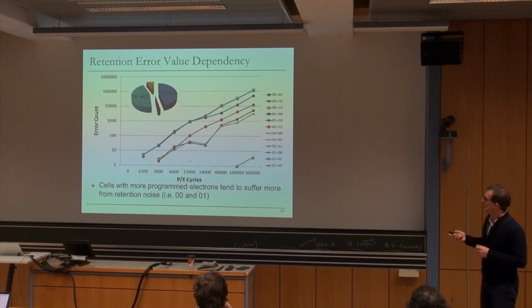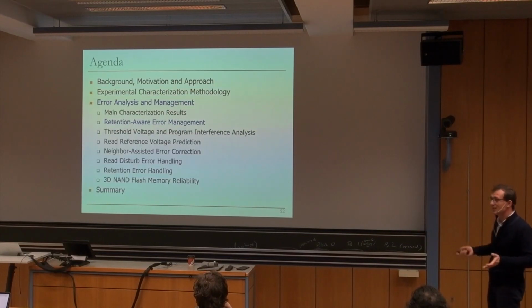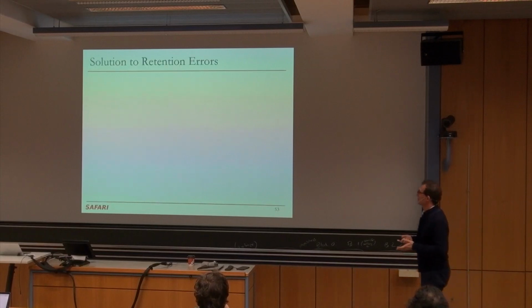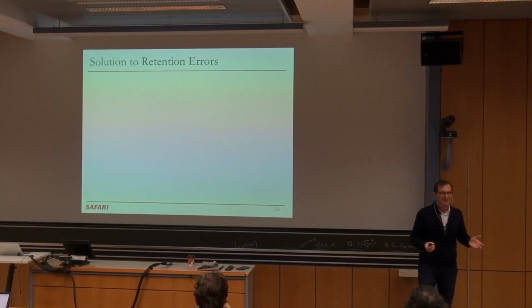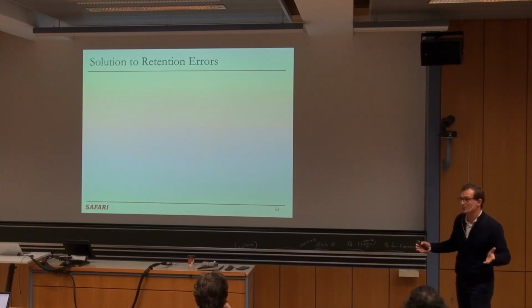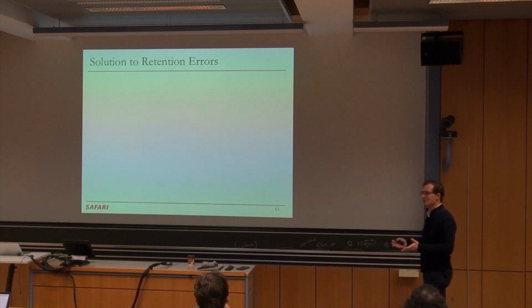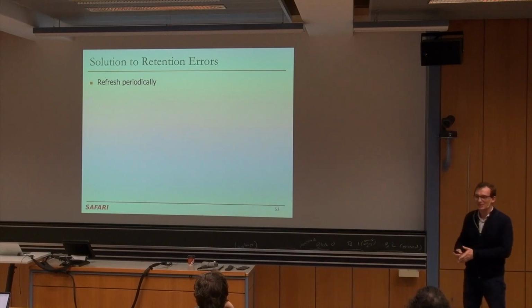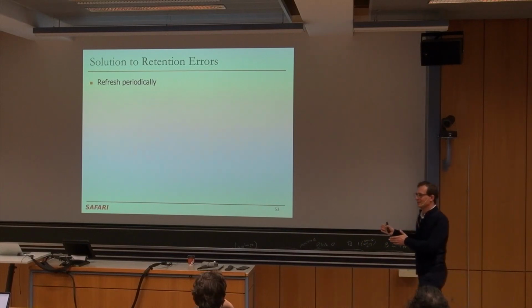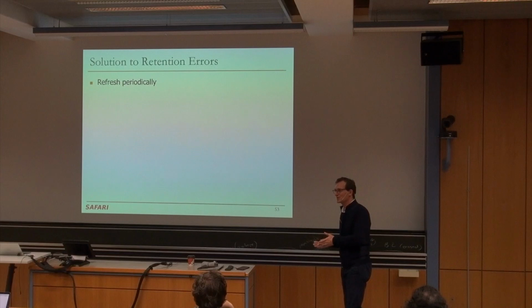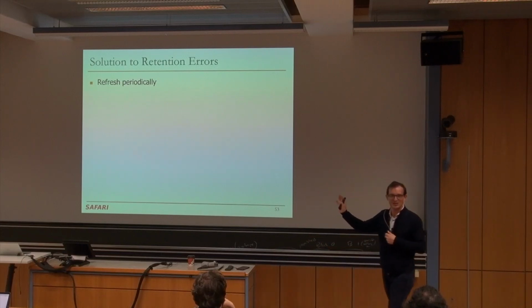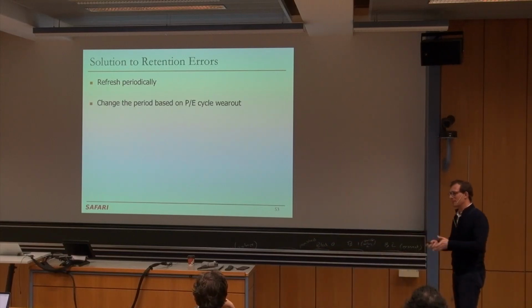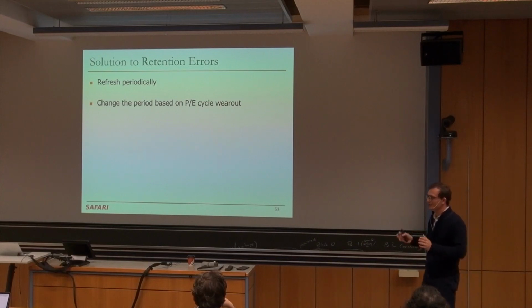Okay, we talked about this. Now we have retention errors. How do you cope with them? Well, you can add ECC, but we already know that that's not a good solution to retention errors, right? Well, we have another solution, which is refresh. And we're going to do that. This is non-volatile memory, flash. And many people don't know that it's actually not refreshed, but now everything is refreshed in flash, especially in data center SSDs where things are powered on.